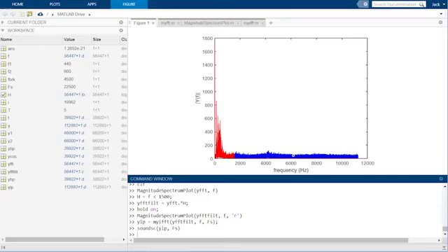Square wave filters keep the entirety of the desired frequencies and completely remove the undesired ones. Often, smoother transition filters are used and have more desirable mathematical and practical properties than so-called ideal filters. For example, one of the most common filters is a Gaussian filter. Gaussians have many mathematical properties that make them desirable as signal processing filters. Let's compare the Gaussian and square wave filter.